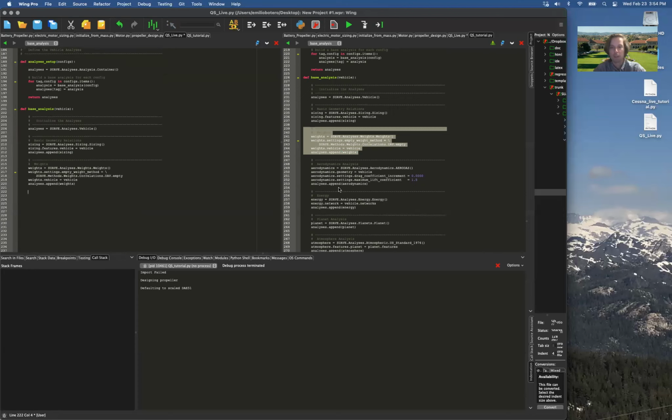The next one is the AeroDes model for aerodynamics. Now there's a paper on this. I'm not going to go through the theory on this, but there's a NASA paper that specifies this is a post-stall model. So this is kind of a necessary feature for any vehicle that's going to transition through stall.